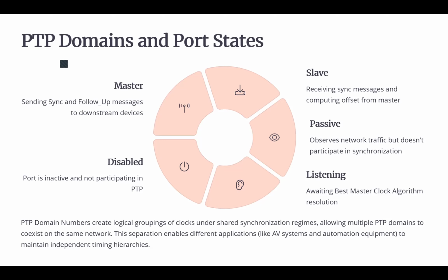Think of a PTP domain like a private clock group where all the clocks follow one grandmaster. The devices in the same domain synchronize with each other and ignore the clocks from another domain.